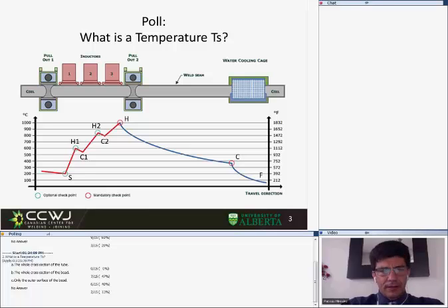When we come out of welding, the temperature distribution through the weld thickness is fairly uniform because welding is through the thickness. It's not coming just through the surface. So it is the outer surface of the bead, and it is also representative of the whole cross-section in this case. When we come out of the weld, the temperature we are measuring on the outside, this temperature at point S, is fairly representative of the average. Of course, nothing is ever going to be exact, but this is fairly representative of the average. And it's a good thing to know because our calculations of inductor power are based on average temperatures.